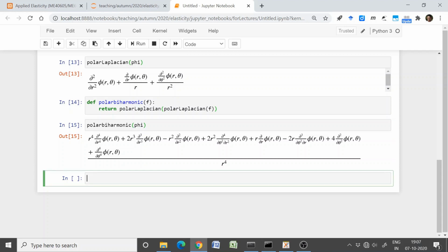All right. So let us proceed now and find out the expressions of the stresses, because when you are doing a 2D elasticity problem, one of the primary interests would be not to stop at the solution of the biharmonic equation. Rather, once you get the Airy stress function in your hand, one of the primary interests would be to obtain the stress fields, and later on of course the strain fields, the displacement fields, like that.